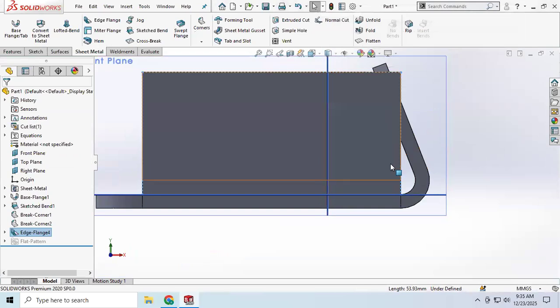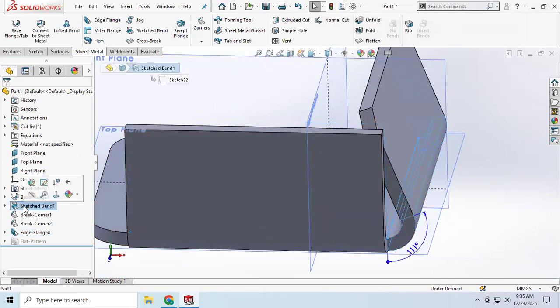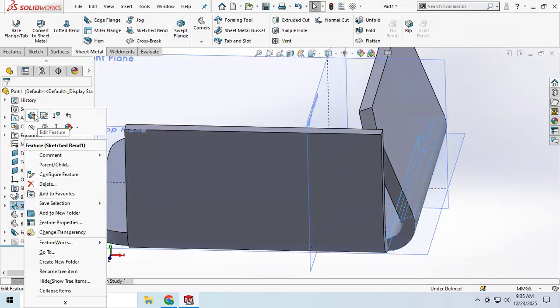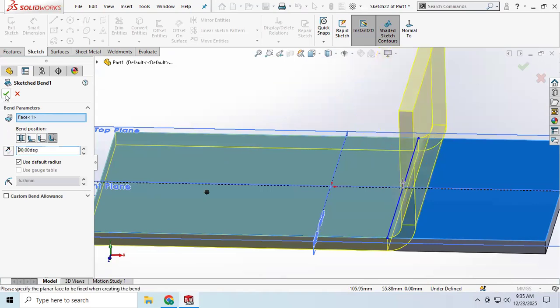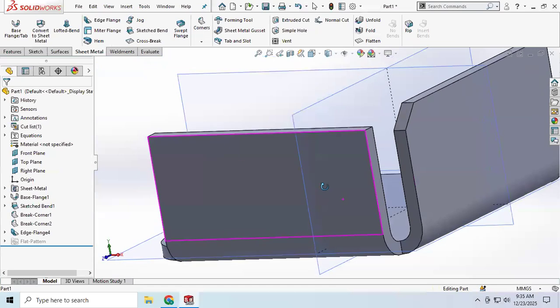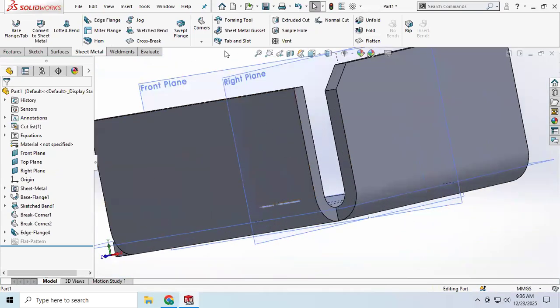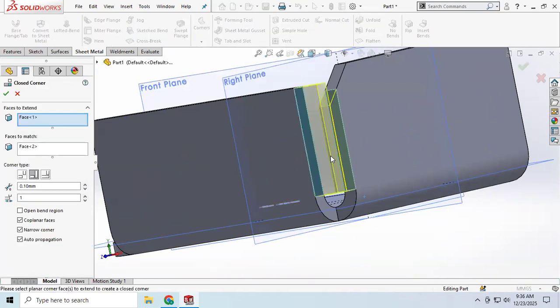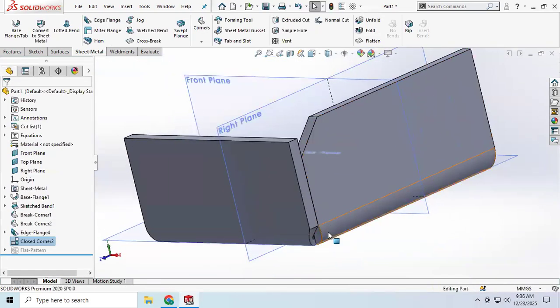This is the sketch right there. One more thing I do again is go to the sketch plane and then go to the edit plane. Then I want to set it to 90 degrees here. Same thing I use. These are my corner points where you want to join. Here we have the closed corners option. If you click on closed corners, this will be closed right there.